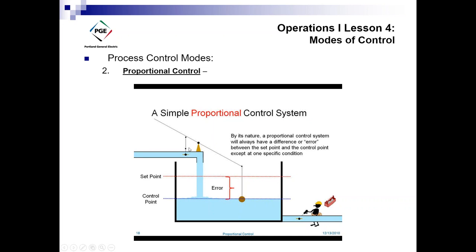Your valve opens. This looks like proportional control, so the lower the level, the higher the flow. So in proportional control the inlet equals the outlet. And you also got to make sure that whatever your system control is can actually match the output. So if you have a valve here and a flow that, when fully opened, can't maintain the flow because there's not enough inflow to match the outflow, then your proportional control system doesn't work.